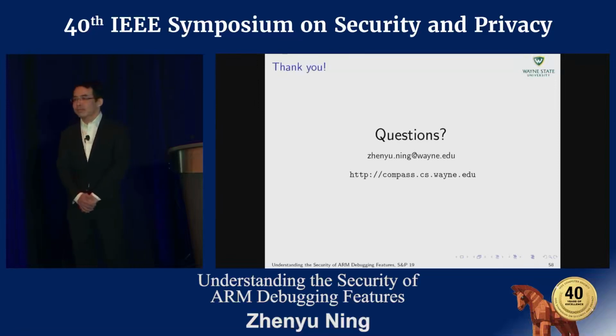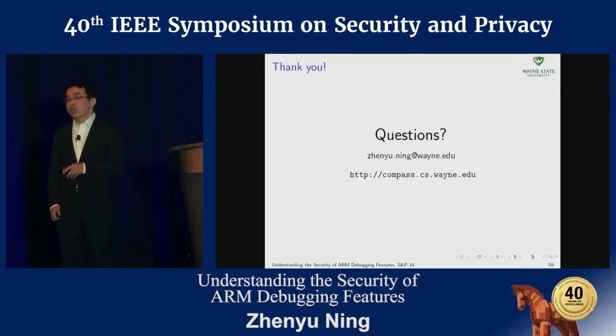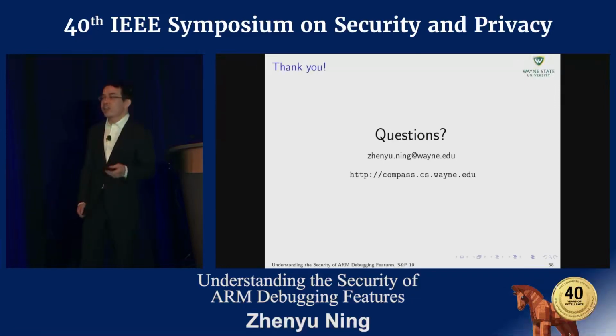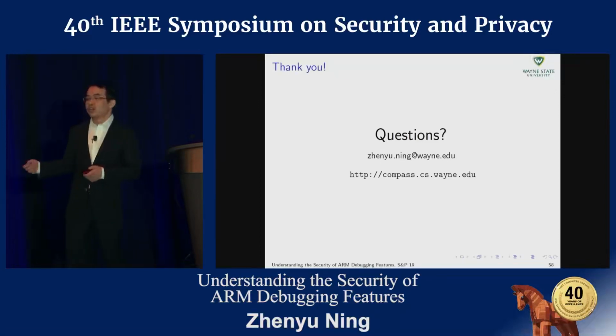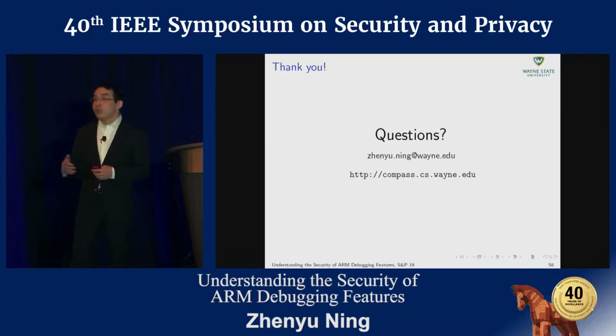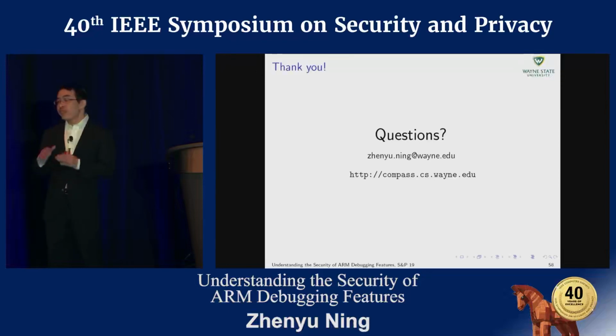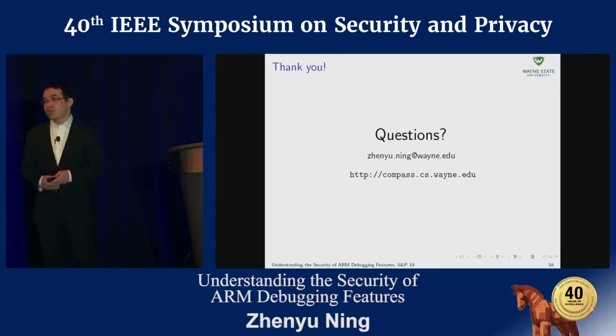So one question that I had is, when you reached out to the vendor, what was their reaction to all of this? Actually, we talked with a lot of OEMs and SoC vendors, but most specifically, the SoC vendor is responsible for the management. So they are trying to restrict the access to the debugging components. For example, MediaTek said that they have some hardware component to define the boundary between the trust zone and the non-trust zone. So they are planning to apply this hardware to restrict the access to the debug registers.